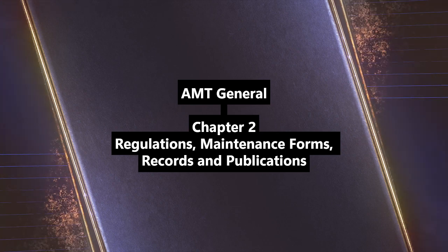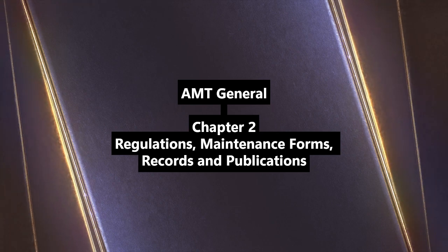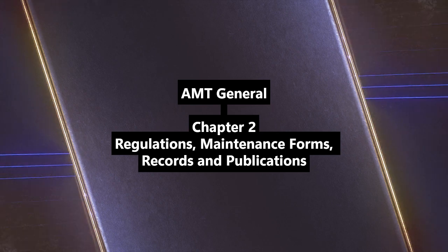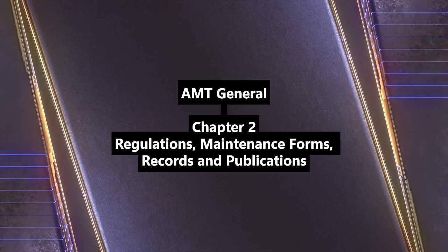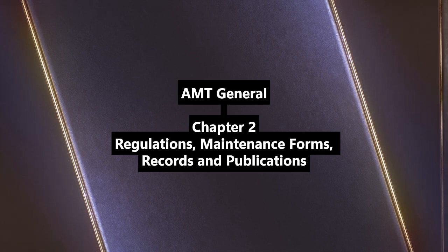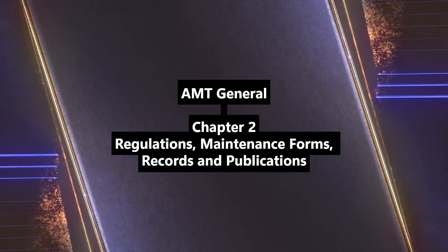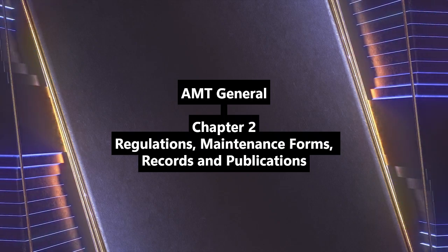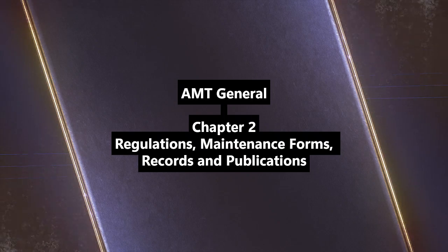Two types, standard and special. Right. Standard, Form 8100-2 for normal, utility, transport, etc. Special, Form 8130-7 for experimental, light sport, restricted, etc., issued by FAA designees, must be on board and displayed at entrance, can be revoked if aircraft ceases to be airworthy.